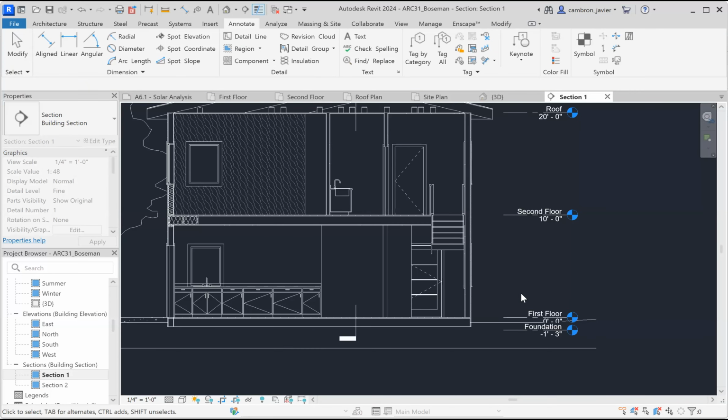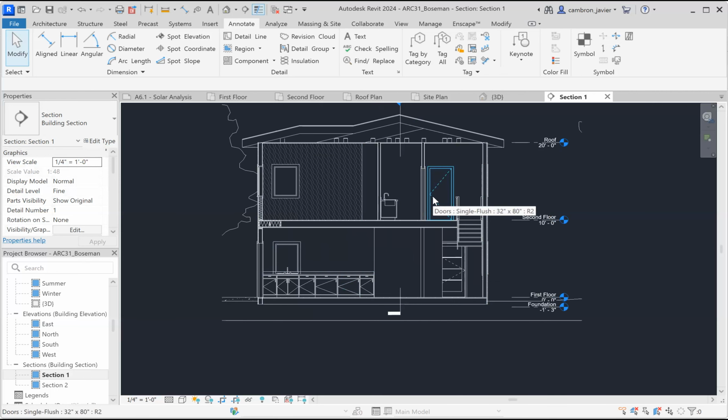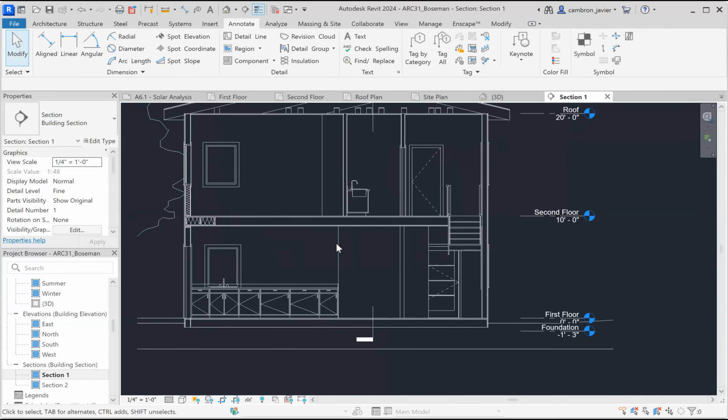And just like that, we're able to fix something in the two-dimensional drawing as opposed to having to edit and manipulate that three-dimensionally. Okay. So the detail lines and these detail tools are really good to hide mistakes or add a level of detail faster than it would be to model the thing out. Okay. So hopefully you can get by with these, and this has been helpful for you.